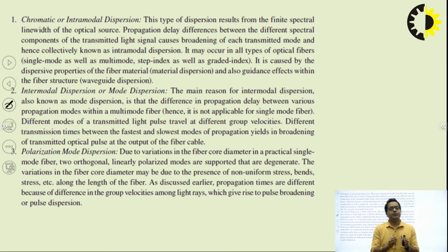The important point here is that it occurs in all types of fiber, whether single mode fiber, multi-mode fiber, step index fiber, or graded index fiber. In all types of fiber there will be a dispersion called intramodal dispersion. It is the result of the finite spectral line width of the optical source.